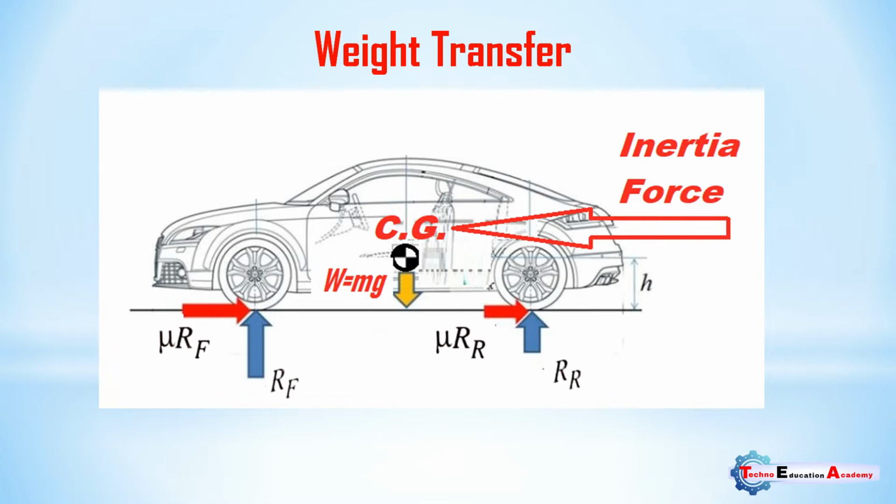However, in such a case, trouble would arise while traveling over a wet road, where high braking effort at the front would cause skidding of the front wheels. Because of the decrease of weight transfer, in practice about 60% of the braking effort is applied to the front wheels.